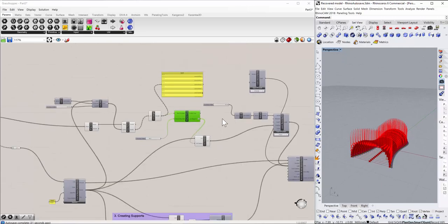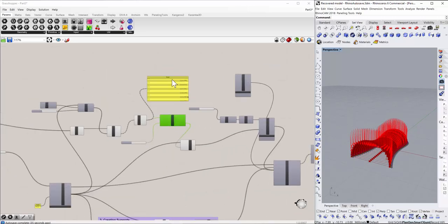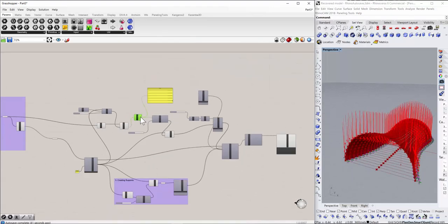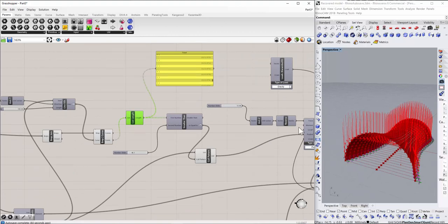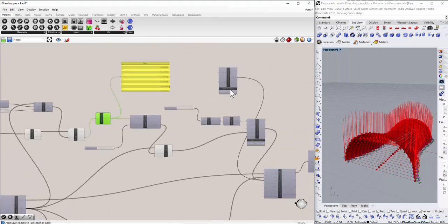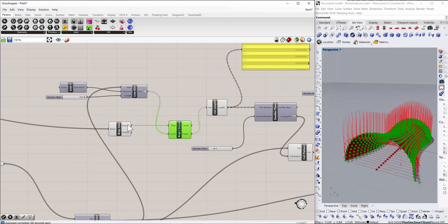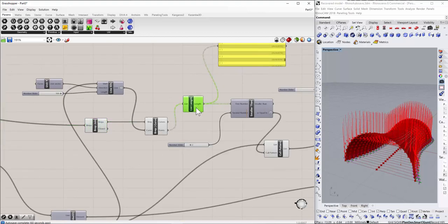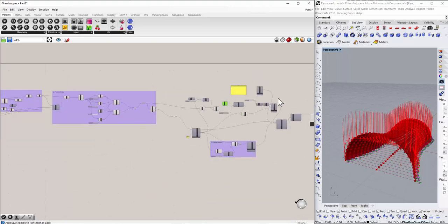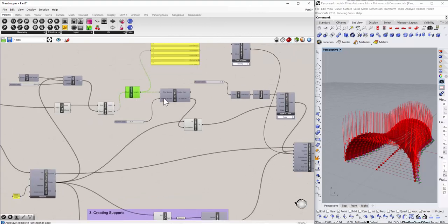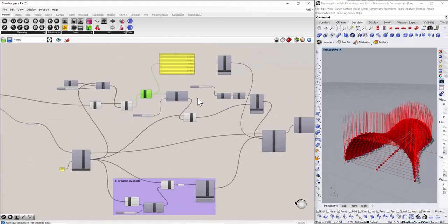And you can also definitely apply forces if you want to apply it exactly on some points, or uniform load forces. You can do that as well. You just need to take the points and the curves and the edges from this data tree, and you can apply these forces in a manner like this, and you can use some conditioning like the smaller than condition here.